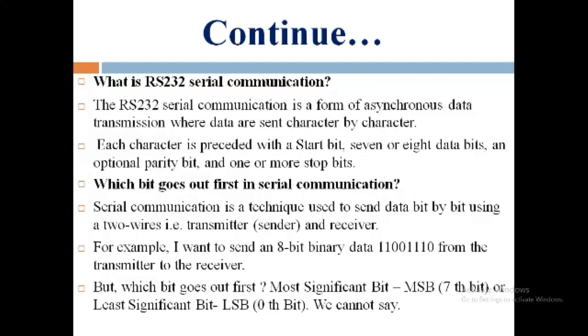Then, which bit goes out first in serial communication? Serial communication is the technique used to send data bit by bit using two wires, that is transmitter, sender and receiver. For example, I want to send 8-bit binary data 11001110 from the transmitter to the receiver.